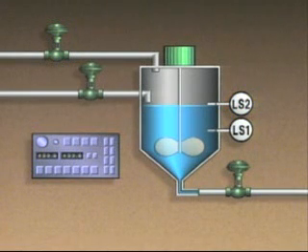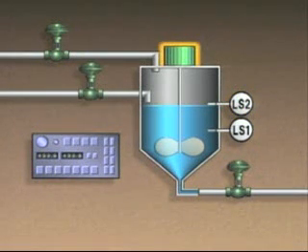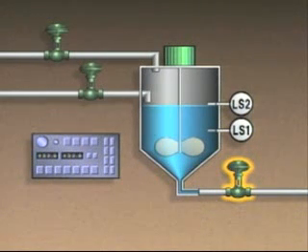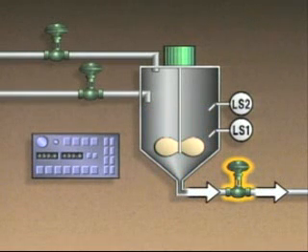The two fluids continue being mixed by the agitator for a period of time that's been programmed into the control logic program. After the mixing period has elapsed, the programmable controller turns off the agitator's motor. Then the programmable controller sends a signal that opens the product outlet valve. The fluid mixture leaves the tank through the outlet line and is sent on for further processing.